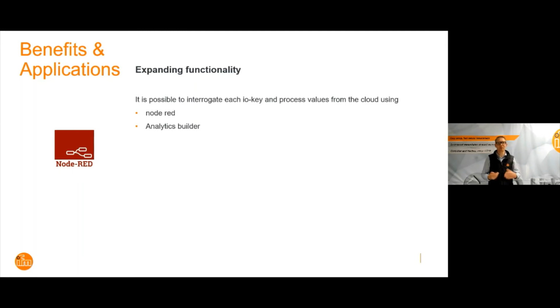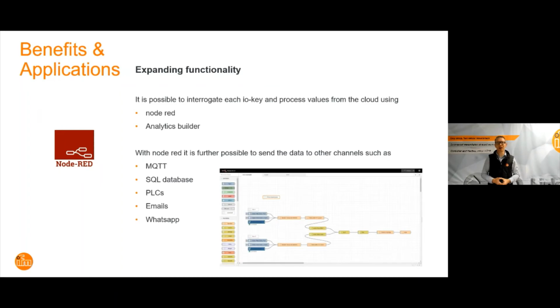And for example, with Node-RED, I have done a few tests and played around with it. It is possible to interrogate the cloud, pull information from the IFM cloud, from these processed data, into Node-RED and utilize it for different channels, such as maybe MQTT services. If you want to push the data into your own database like SQL.